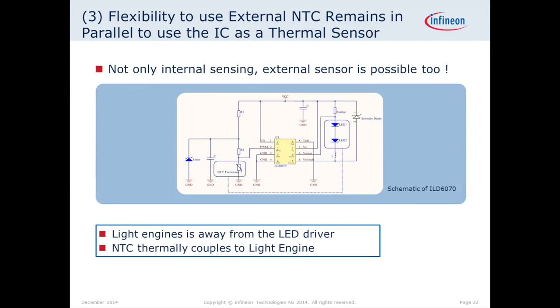Now, what is advanced? One further point: we always said you may not use an NTC if you can thermally couple the LED driver IC with the LEDs. But what happens if you cannot? In some cases, these DC-DC LED driver ICs are implemented in the LED driver, which is further away from the LED light engine.